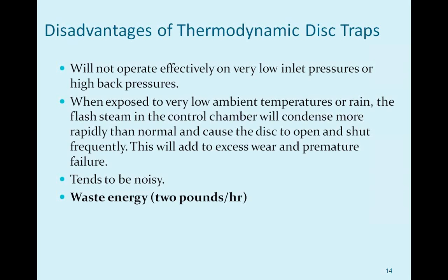In fact, probably a dozen years ago, I was out doing a steam survey, and to test traps at this one facility, one of the maintenance people would actually just drop some water on it to see if it would cycle. It was hot out, but he would just pour a little bit of water on the top of the trap, and just that little cooling would cause it to cycle. But that can be an issue if they're outside and you're in rain or something like that. You might be passing steam where you don't want to. They're noisy traps, and like we said on bucket, these will waste or use some energy.